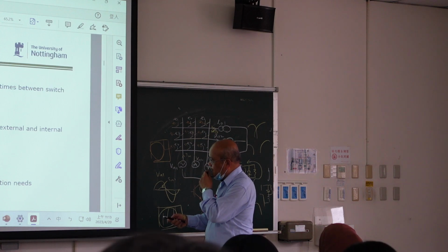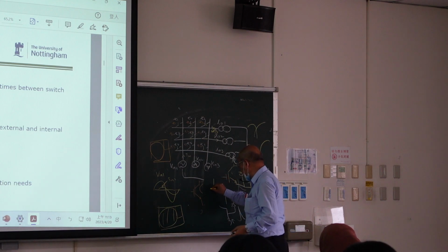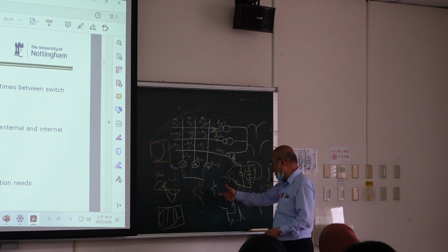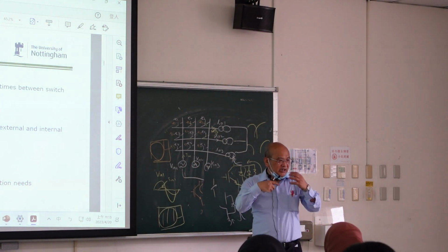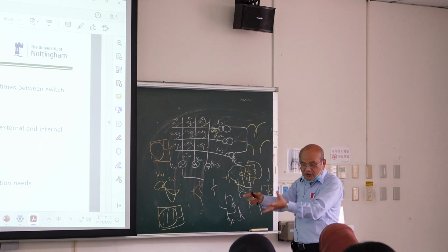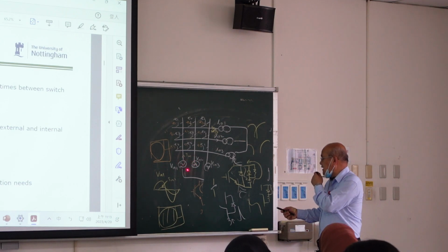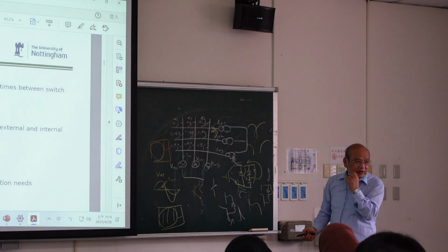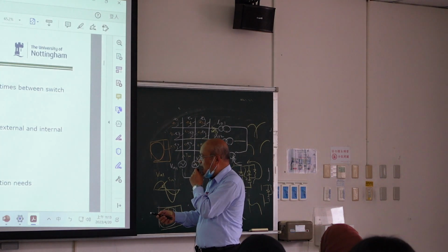If the DSP fails, then the DSP makes the switch on. Then this switch turns on, this switch turns on, and short circuit. Because DSP sometimes turns on the switch, sometimes turns off the switch. But in some cases, if the DSP does not provide any signal, it is turned on, then short circuit. So you have controller function protection.